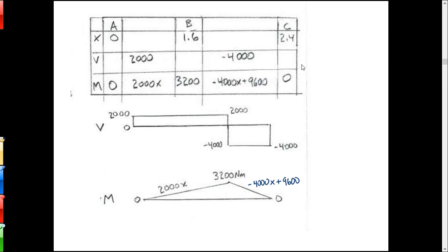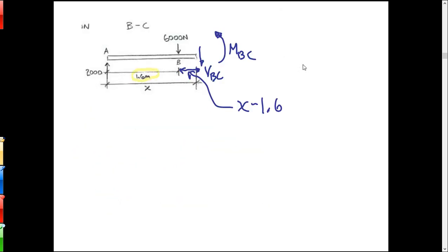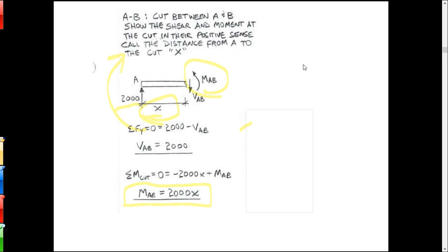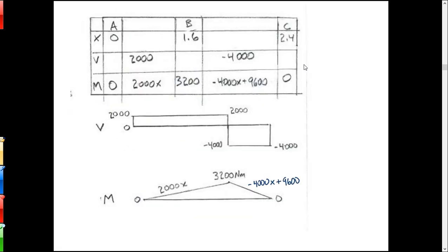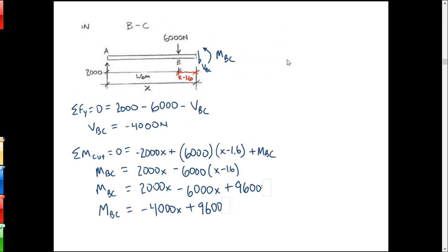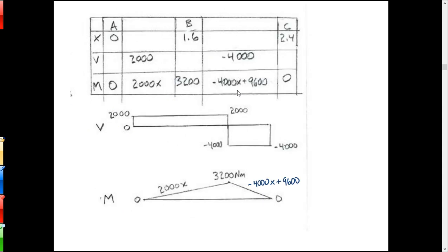Now, if I were doing a structural software program, I'd program my software to come up with these equations, and I'd plot up the equations. So I'd have an equation, and with that I could find the shear and moment anywhere. But also you can make plots of them. So it's very common to come up with shear and moment diagrams, they're called. And there's actually rules to draw those up kind of from scratch without having to generate the equations. If you know a few rules, you can draw up a shear diagram and a moment diagram.